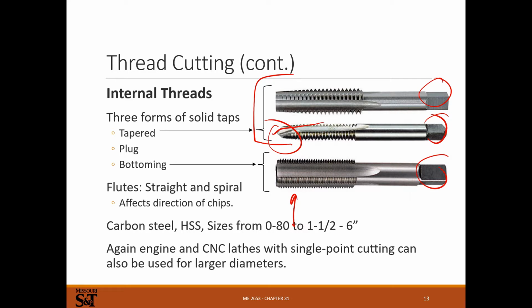This has got a lot of taper on it to help you get started. Trying to start one of these, it's not going to happen. You're not going to start tapping a hole with a bottoming tap. It's got to be lined up perfectly. It's going to be really hard to get it started correctly. So if you need threads all the way to the bottom of a hole, you're going to start with one of these that starts easily, and then you're going to switch over to a bottoming tap if you need threads at the bottom.